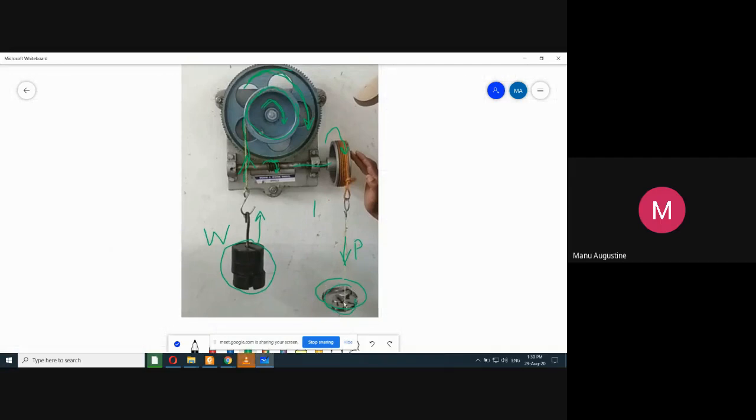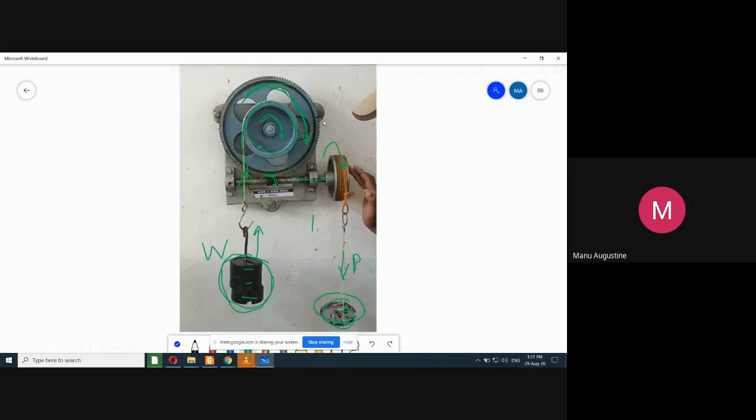Now the most important thing to notice in all of this is the effort. So many tiny pieces of weights are just put over here. This is your simple effort. So this P is so small that this small amount of weight is actually managing to pull so much heavy weight. The weights attached over here are so big, at least 1 or 1.5 kg per block. So nearly 5 to 5.5 kg is being lifted, and you are applying so little effort. So this is actually how you gain the mechanical advantage. I hope the mechanism is clear to you from this image. And now let us see the mechanism in actual working, because I have a video for this one also.